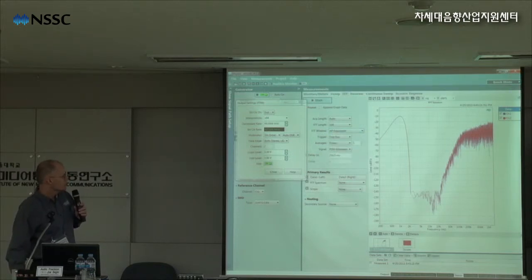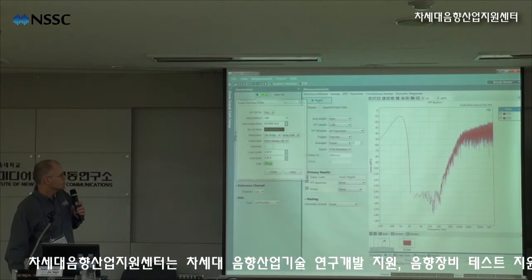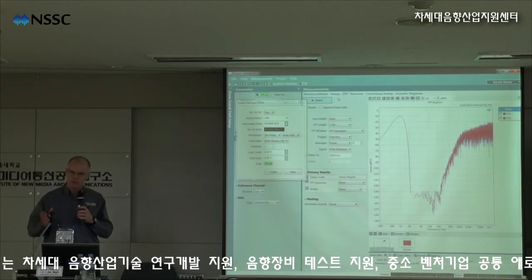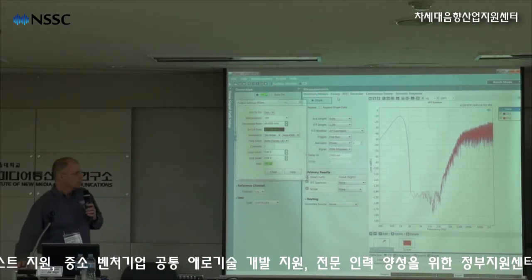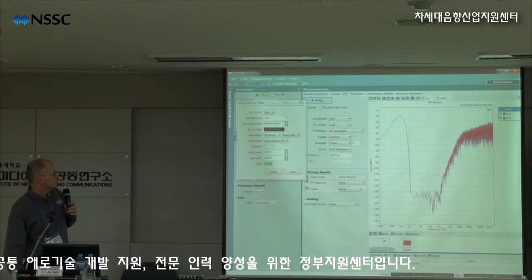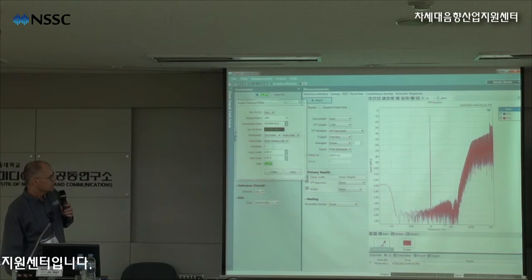I'm sampling basically at the bit clock rate of 3 megahertz, and to see something I would have to bring my FFT length up to a much higher resolution. So let's go to 1.2 megasamples. Now to take 1.2 megasamples at a low frequency like 48K, your acquisition time will be very long. But at this clock rate, it will not be very long. It's very fast. So you can see some of the noise shaping going on here in the background.